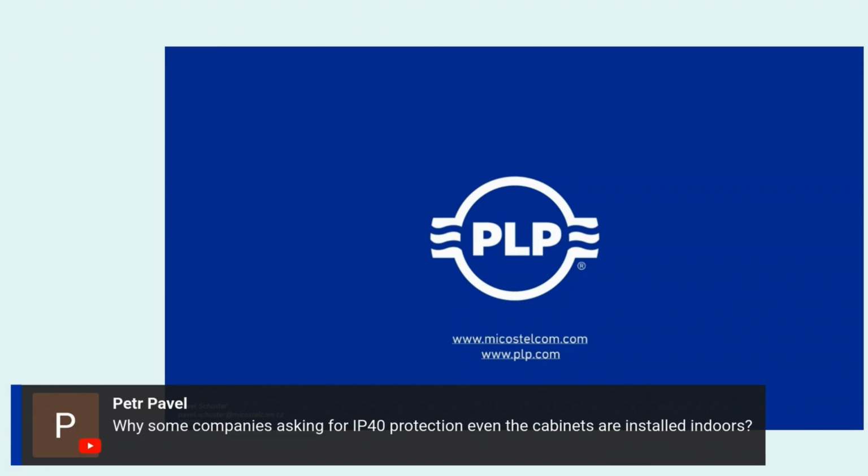And second issue is that IP40 means that there are only 1 millimeter holes in the enclosure. It means somebody could put, for example, some kind of stick or nail or wire inside and damage the fiber optic cables inside. So that's the reason why some of the companies ask for IP40. It's about the protection against dust and against vandalism.